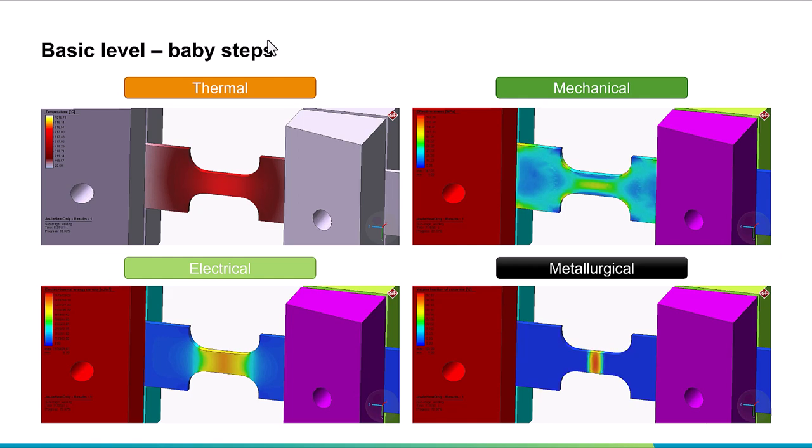This is very interesting because you could design your sample shape, how you're going to have the cutouts here. You can drive the thermal in a certain way and have the metallurgical transformation happen in the specific locations that you want. You don't need to guess how the current is going to flow. You can calculate that, for example, looking at the current density, and understand how the electric part is flowing, how it's going to generate temperature in that case by Joule heating, and how much stress you're causing in the sample by heating it up that much.